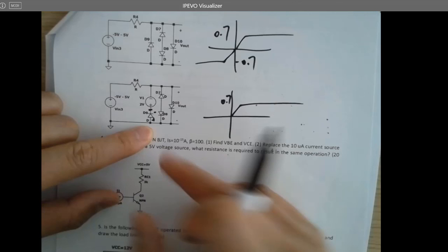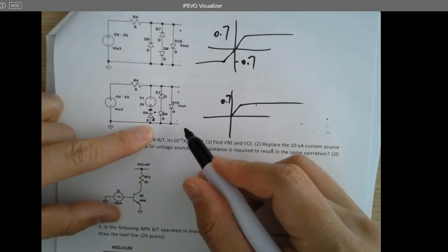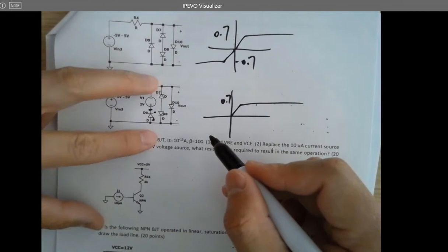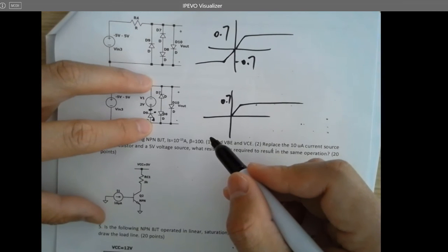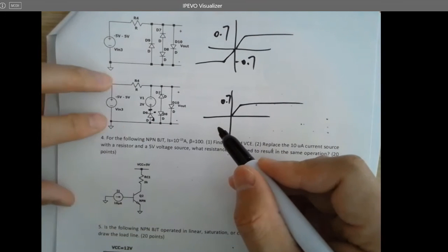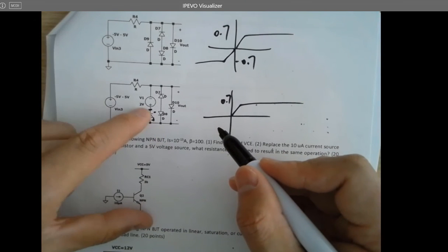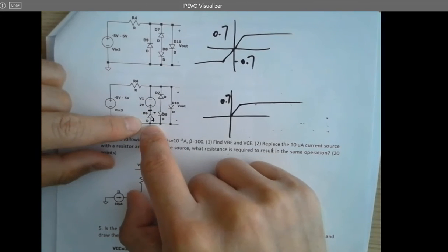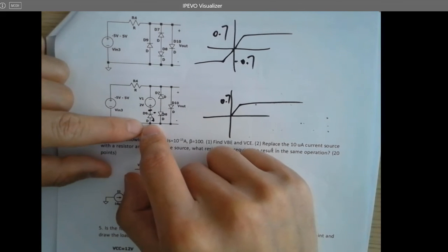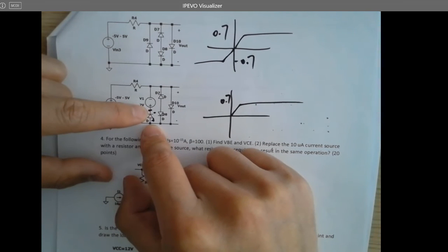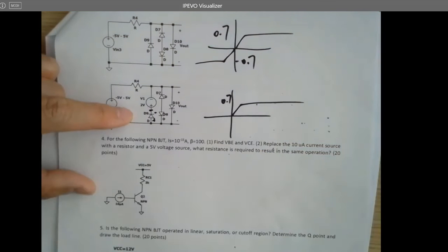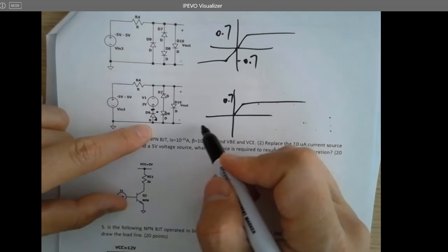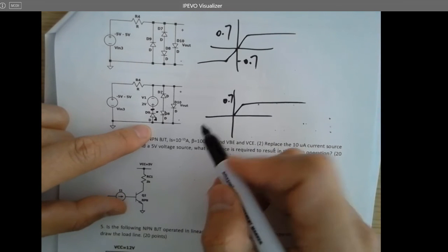So whenever the voltage reaches that point, it won't go down anymore, because current is going to flow in that channel and it's going to be stabilized at that voltage level. When you give a negative voltage over here, which means this is higher, this is lower, you have to give a 2.7 volts drop at least, because this guy is lifting the cathode by 2 volts. So you need 2.7 volts to make it 0.7 volts higher. So what's the voltage here? So 1 is going to be clipped.